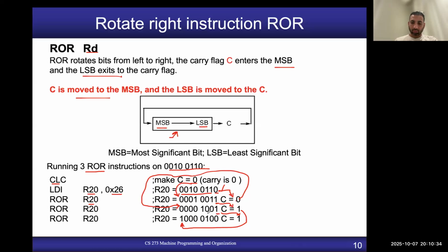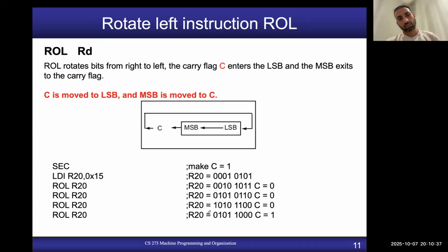No? Okay. So here is another instruction, which does exactly the same thing but in the reverse direction. It is rotate on left through the carry flag. So here, your most significant bit enters the carry flag, and the old value of the carry moves into the least significant bit of the register, right?